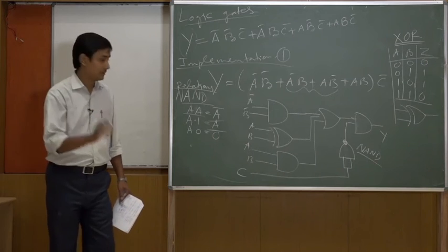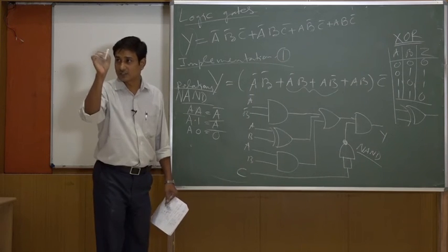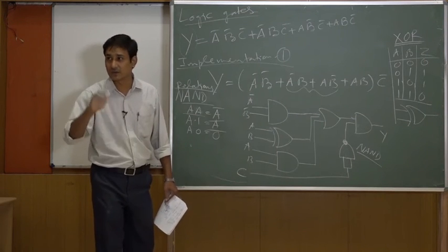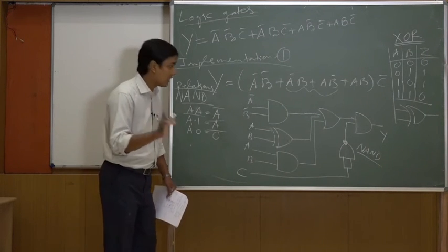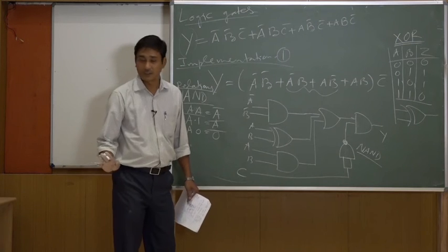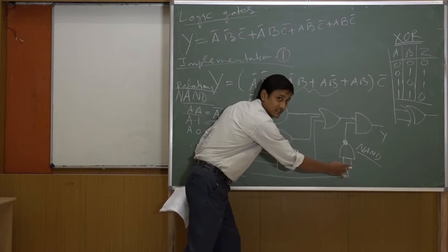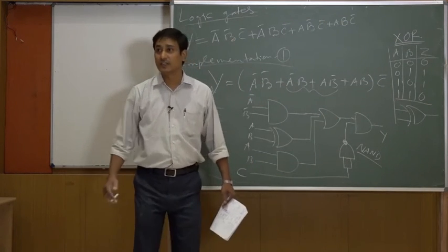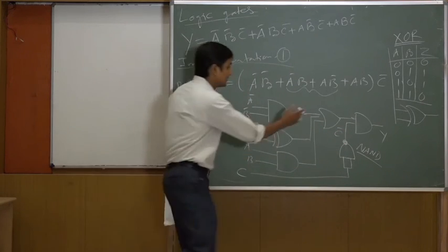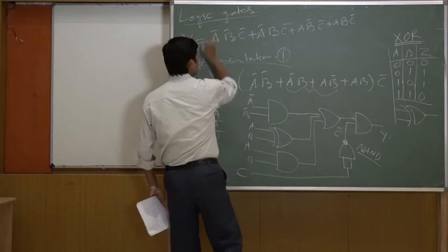Okay. Now, in the truth table, the final output Y was 0 for 0 0, 0 for 0 1, 0 for 1 0, and finally 1 for 1 1. Now it is inverted. For all the remaining 3 it is 1 and the last one is 0, this much only. Since I have only a NAND gate there, no NOT gate, I take this C and apply it to both terminals, passing it through the NAND gate so that I get C bar here. Then this C bar and the remaining part has AND, and finally this is the same expression we started with.